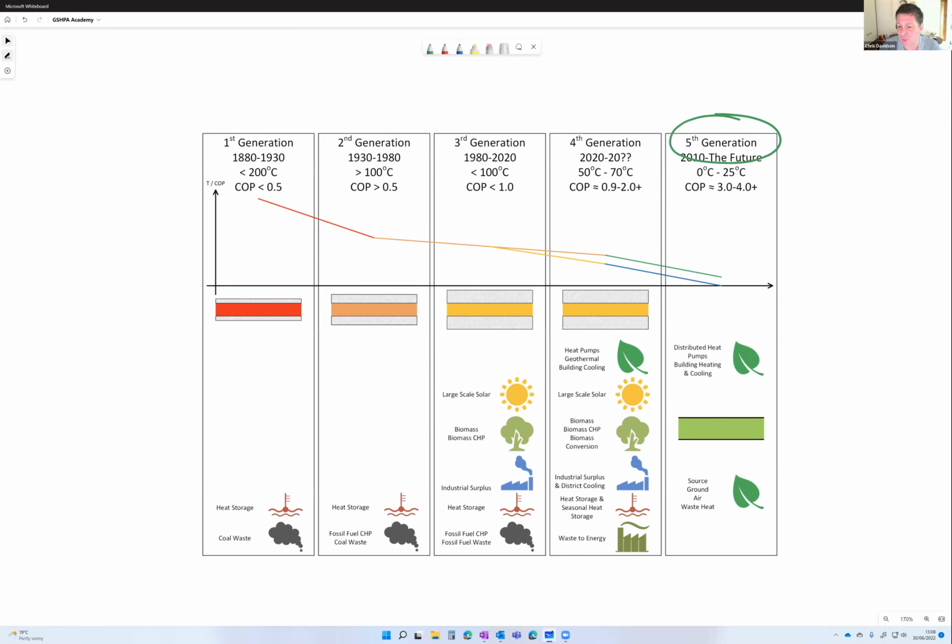They'll be either running for central air and ground source heat pumps or a ground loop. There'll be uninsulated pipe moving that water around to the heat pumps, which tend then to be distributed at a building or even distributed around a building. So a very different heat network architecture, by which you've got lower temperatures, potentially uninsulated pipes, certainly below ground, distributing that energy around at effectively ambient temperatures. Heat losses, therefore, become not a problem, but a benefit. So when we start to run those heat networks down below the temperature of the ground, they suck heat from the ground. So they've got negative losses in that regard.